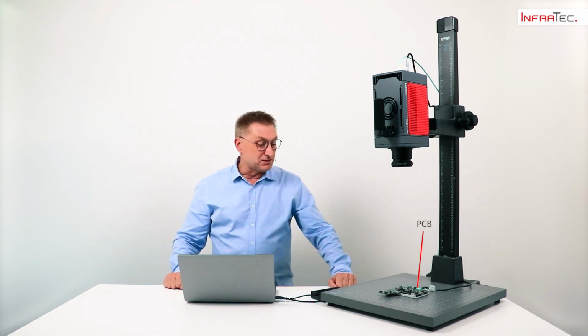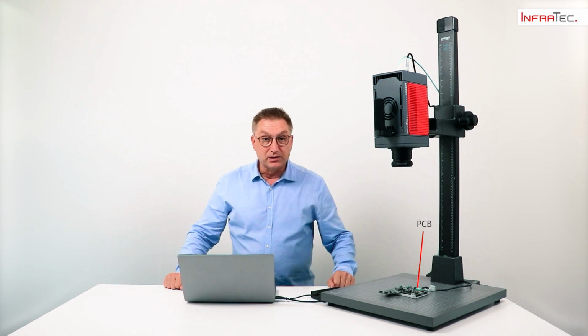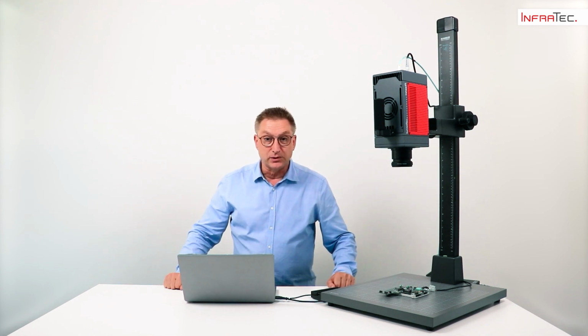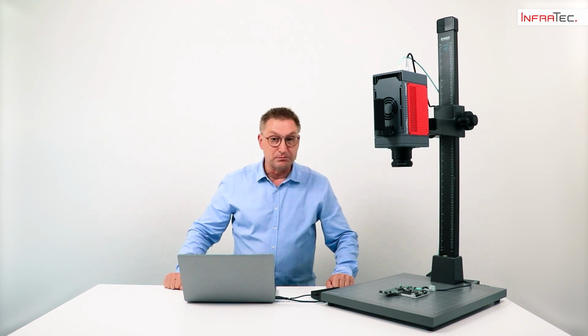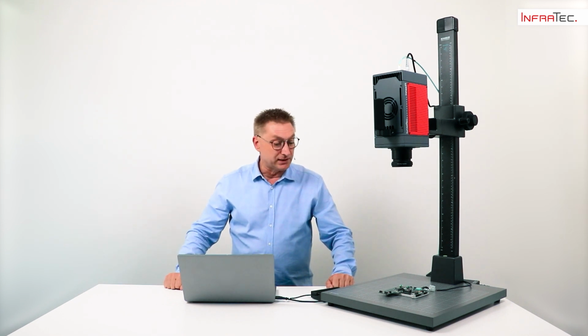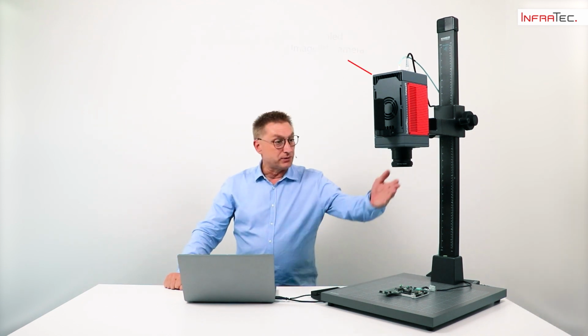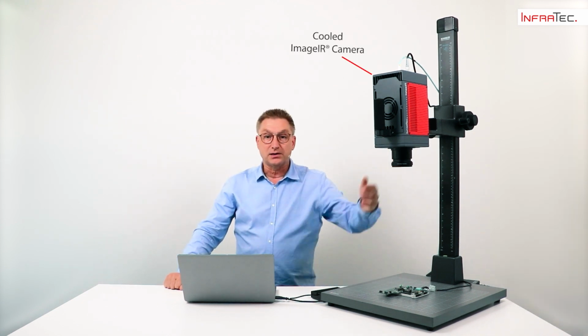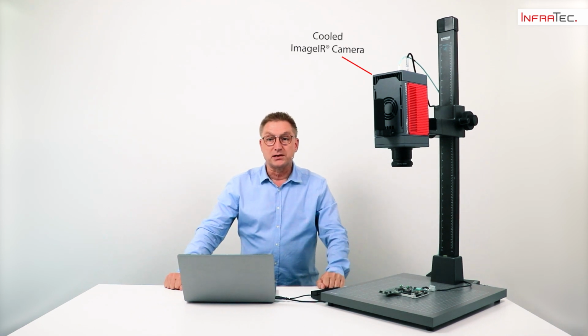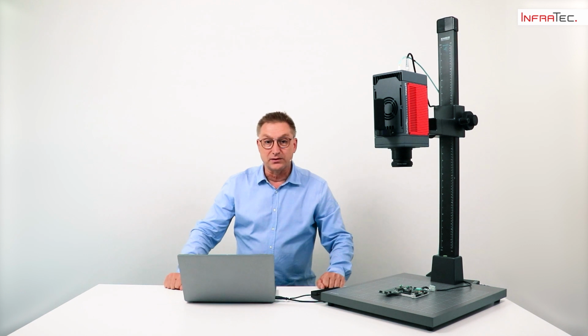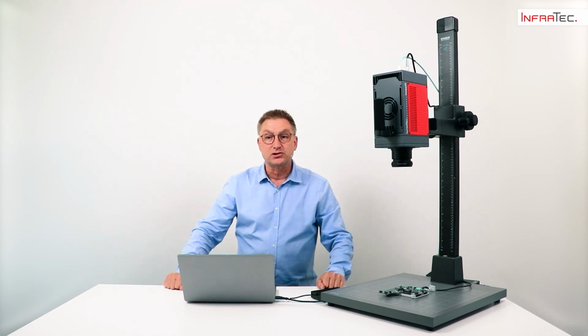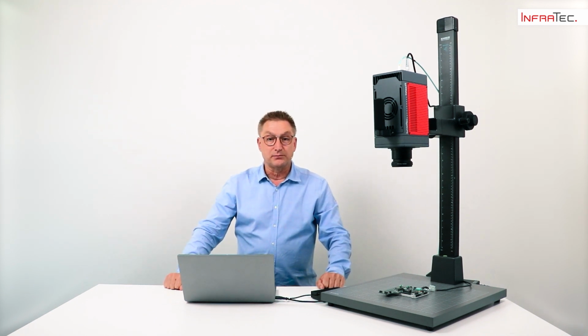This PCB consists of a wide variety of components with different surfaces, which all influence the emissivities of the different parts. So these need to be corrected later on with our software. The measurement itself is carried out with a high-resolution IR camera in order to be able to measure even very small hotspots on small parts or components on the PCB, and to avoid geometrically induced measurement errors.